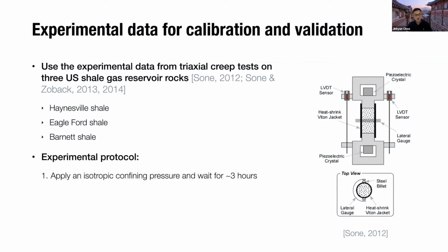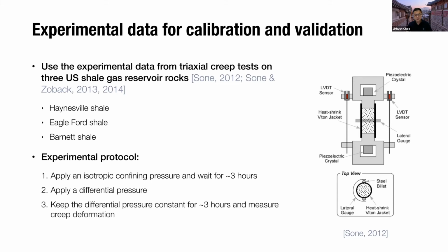Firstly, apply an isotropic confining pressure and wait for approximately 3 hours. And then apply a differential pressure. And then keep the differential pressure constant for about 3 hours and measure creep deformation during this constant differential pressure stage.